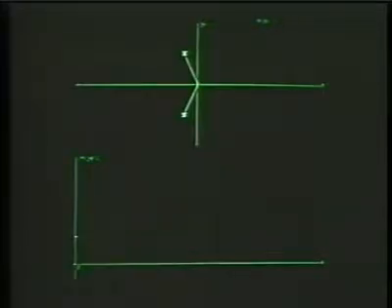As we move vertically along the j omega axis and the pole vector lengths change, that will influence what the frequency response looks like. We've started to move a little bit away from omega equal to 0, and notice that the pole vector for the pole in the upper half plane has gotten shorter, while the pole vector for the pole in the lower half plane has gotten longer.